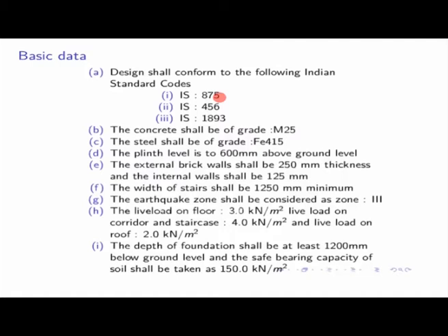I am talking about live load or imposed load. If we consider an assembly building, what will be the load? So different cases you will have. Then you have a staircase, how much load shall we consider? If it is a balcony, how much load shall we consider? Obviously it all depends on the different kinds of utility. Let us consider the balcony. In a balcony we consider, say, 4 kilonewton per square meter load.